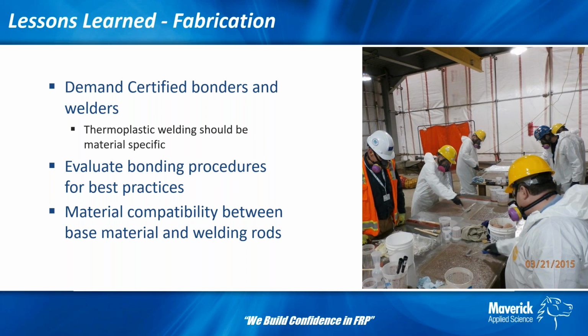And one thing I wanted to mention specifically with thermoplastics is material compatibility. CPVC is not CPVC. What we find is that the base materials are the same, but when they make tubes, flat sheets, welding rods, and fittings, there's a little bit of difference in the background chemistry to make it more moldable, to give it better mechanical properties, to give it more flexibility, whatever the concern may be. So they do add some things. It's important that particularly the welding rods they use are compatible with that specific material.